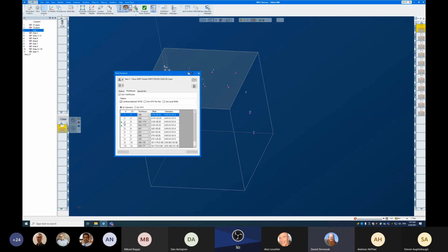So that might be a part station WFO, like a G54, or part instance WFO if you're using multi-part. It might be a native local WFO, in other words, one that's actually using the origin from the op CS. Or it might be a borrowed WFO where we're using an origin from a different operation or something like that, all of which is now possible but was not previously.